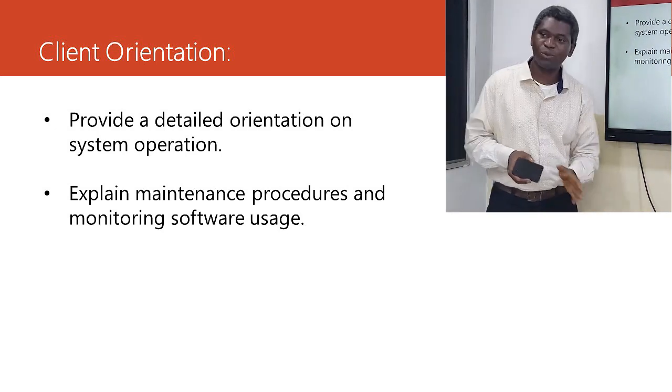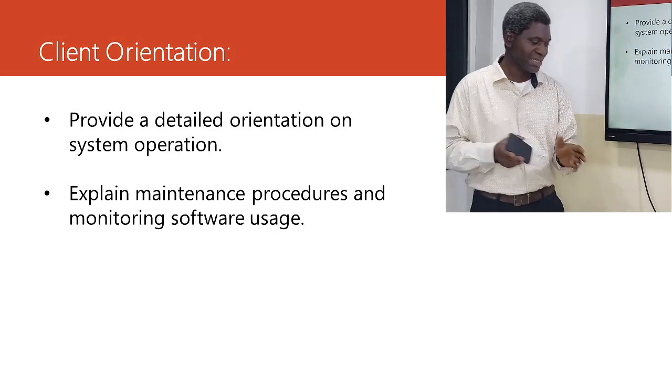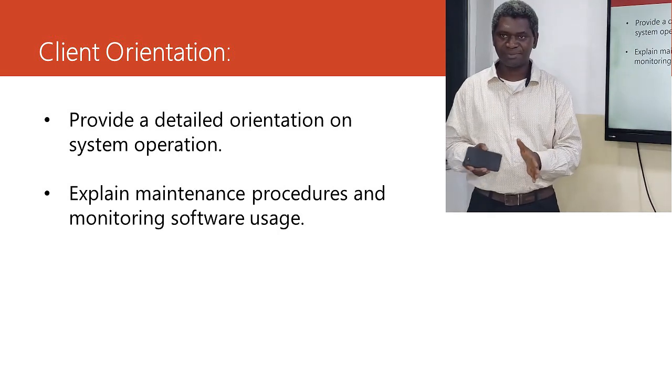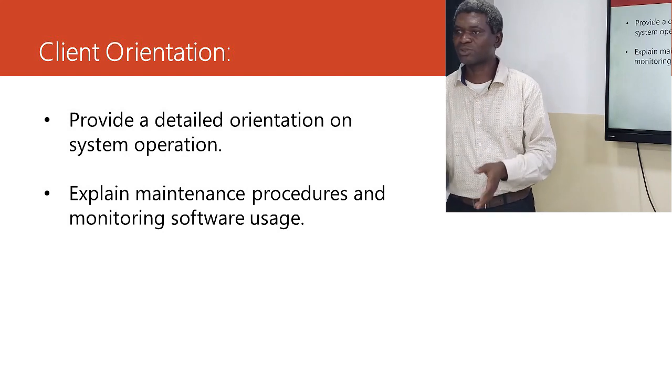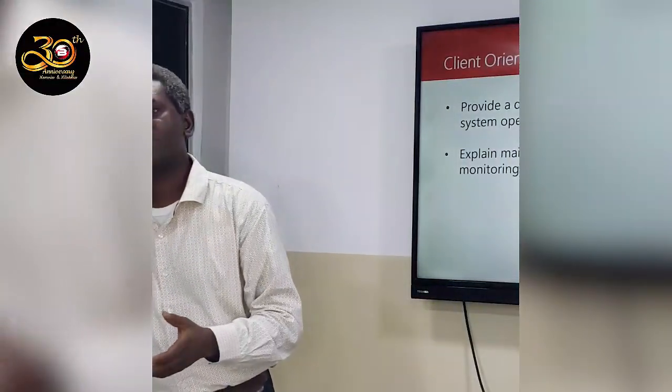So explain to them what the system can power, how to use it during the day, during the night. For example, now, a 1.5 kVA system, somebody is putting a freezer on 1.5 kVA. How? It will not last. 1.5 kVA with one battery, 2 panels.